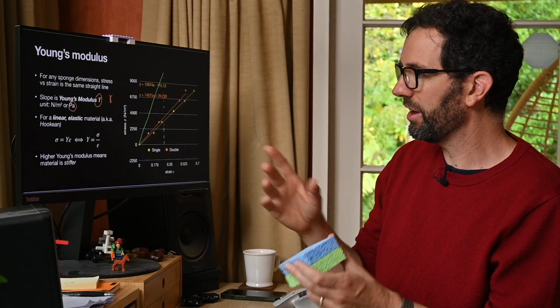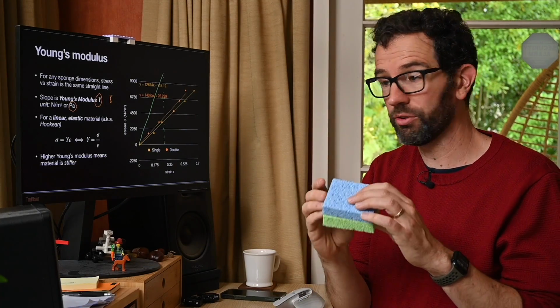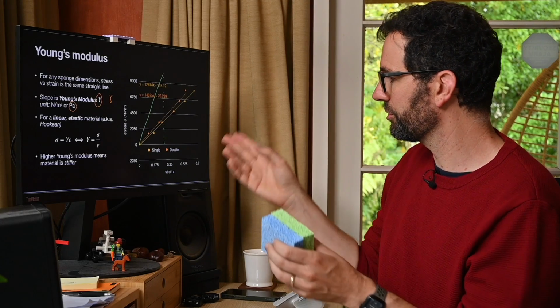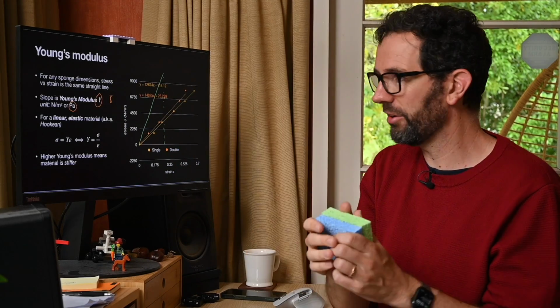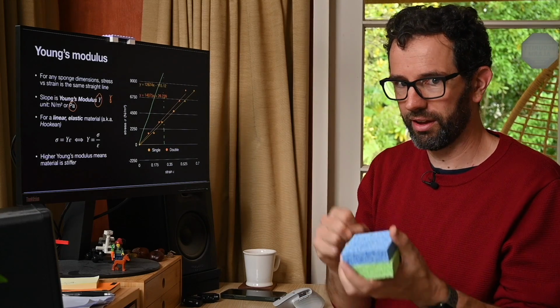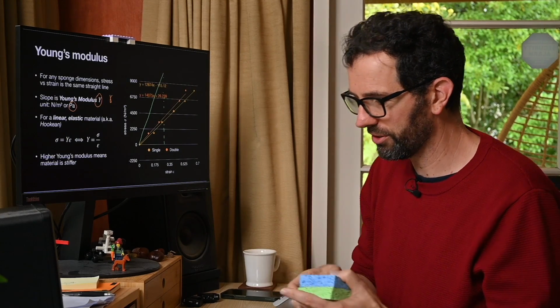Okay, so Young's modulus, that is a property of the material that you're studying. And then you just grab the dimensions, which is like the thickness and the area, to relate the force and the compression together once you know this Young's modulus.